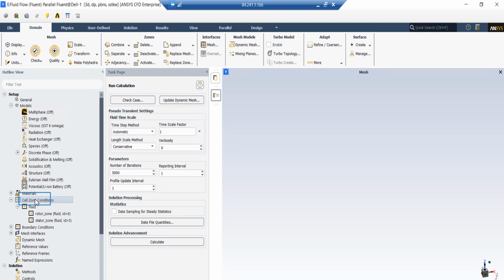In our cell zone tab, we're going to the rotary zone, which is the inner cylindrical zone, and we're going to select the mesh motion condition. Afterwards, we give our rotary zone a specific angular velocity, an axis for rotation, and also a single point as an origin for our rotation axis. By doing these setups, our solver would understand how to rotate our body, and by rotating our rotary zone, we're going to observe how the airflow is going to vary due to this rotation.